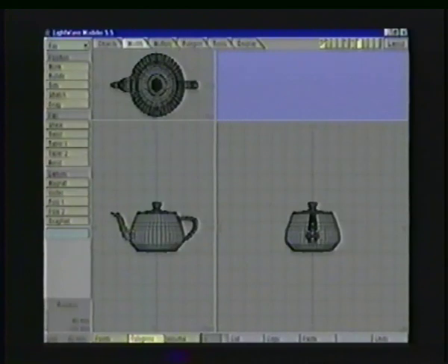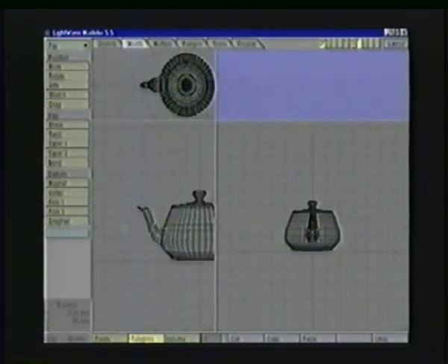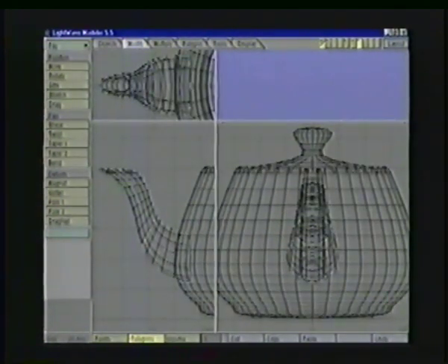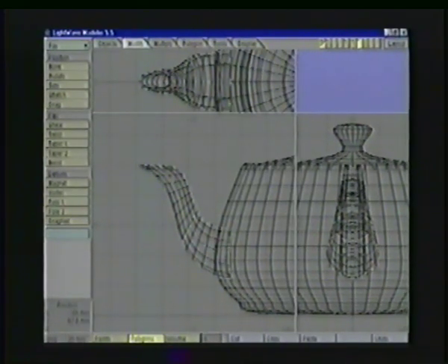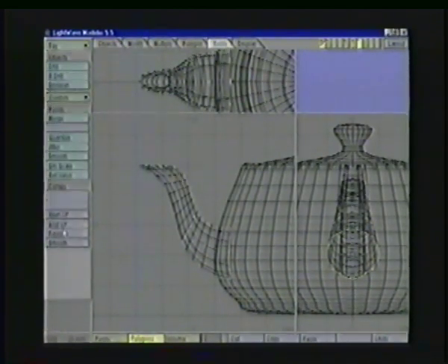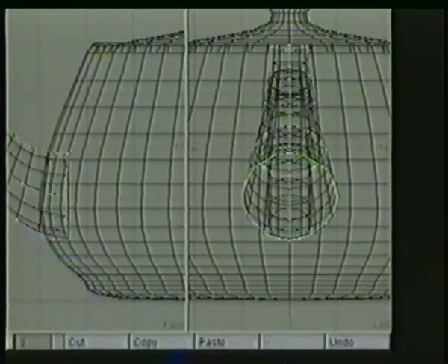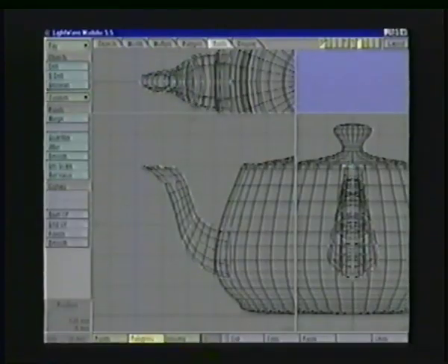I think that'll look good. And once again, I'm going to zoom into the spout. We're going to need to do the exact same thing to the other ones. It's a simple matter of selecting both spline curves, going to Tools, Smooth Curves, and you can see it smoothed right across that gap. Some may be less obvious than others, but in the end, it's going to help.